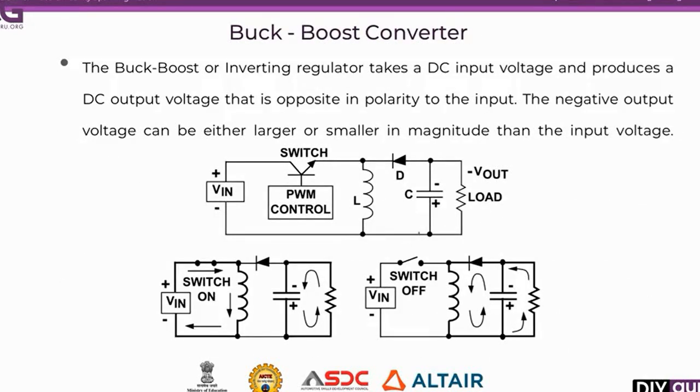Now we will see the buck boost converter. See, in the buck boost converter, you can either increase the voltage or decrease the voltage at the output, that is across the load RL. This is mainly done using the duty ratio delta. This is also denoted as D. In some textbooks they will denote this as D, or it may be delta. This is the duty ratio.